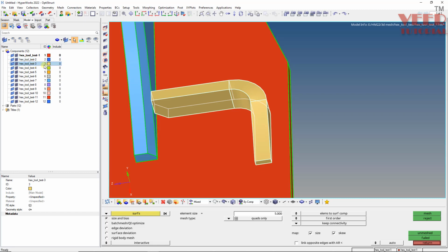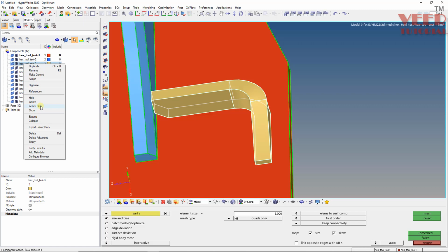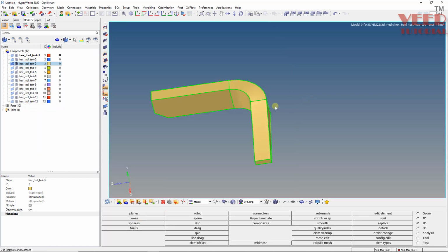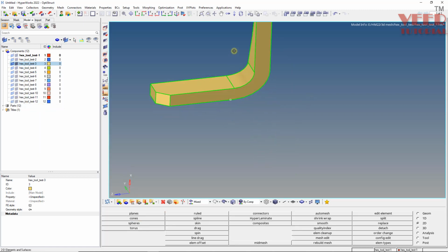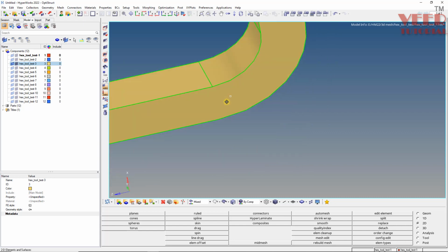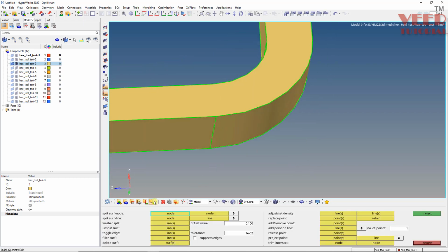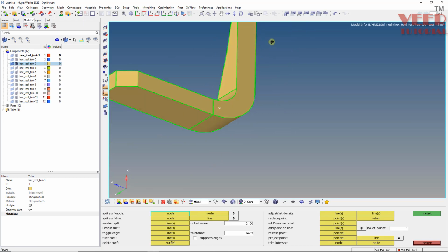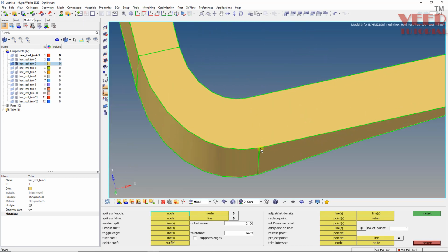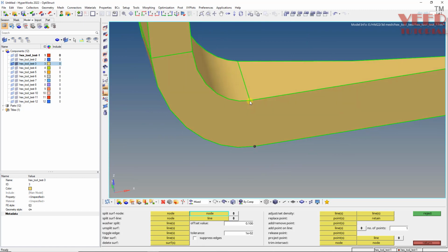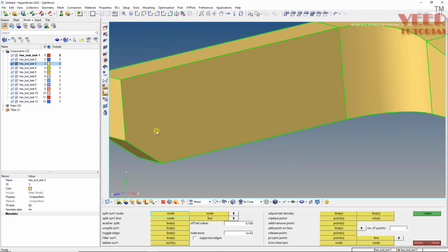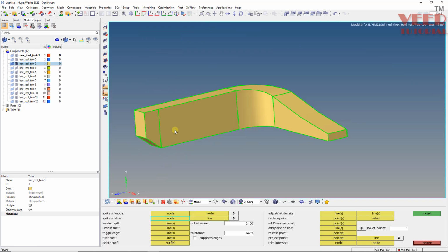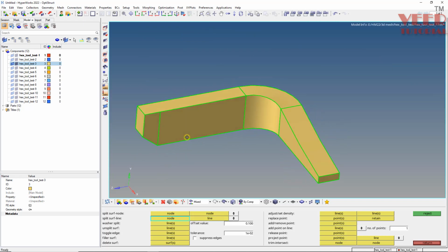For this, click on this arrow, then select this part. This is my part number 3. Right click and isolate only. Similarly from the bottom I also want this cut here. So F11 from this point up to this point. Similarly from this point up to this point. We can also take one split here from this point up to here. Okay, now let's start the mesh.